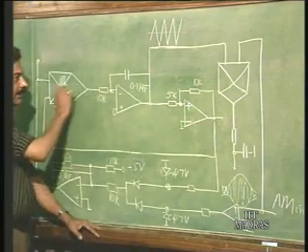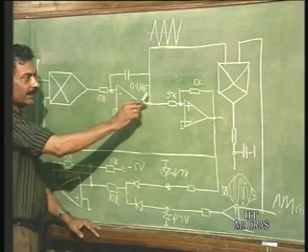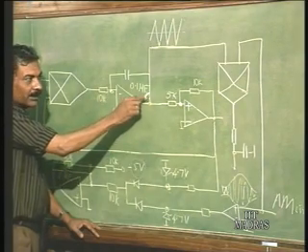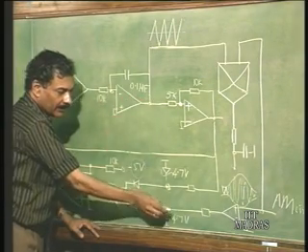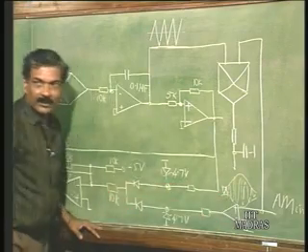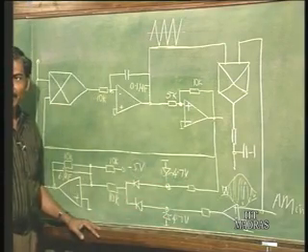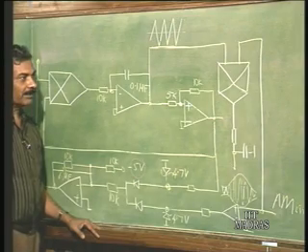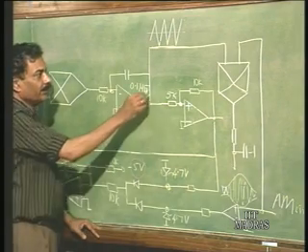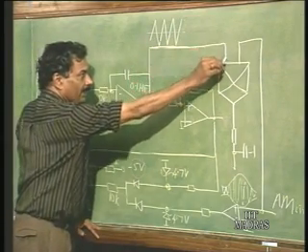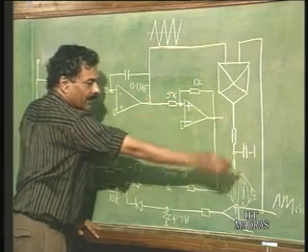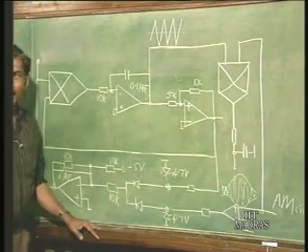That is already done by this VCO, that is an integrator. If you take the triangular wave output, this will be in phase with the incoming sine wave or this particular carrier. Okay. So, in this part of the experiment we will see that if you take the output here, it will be a triangle with the same phase as the incoming carrier.